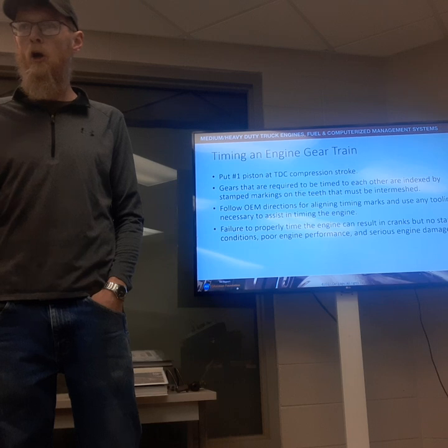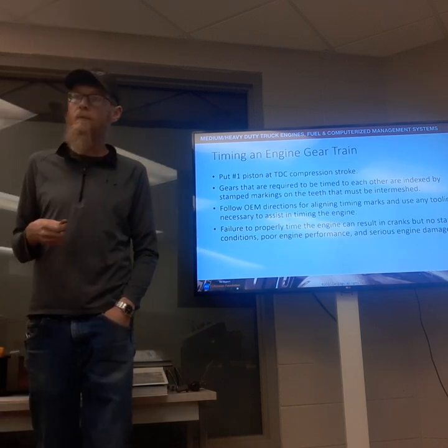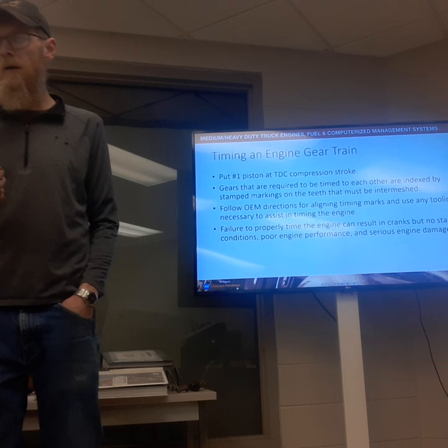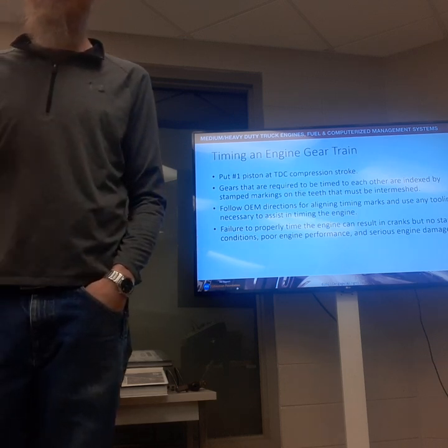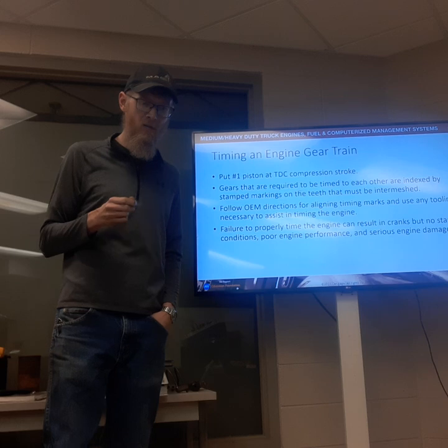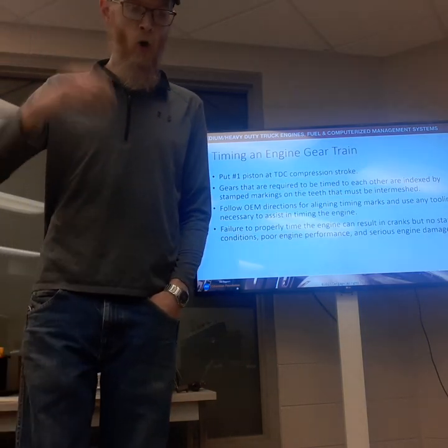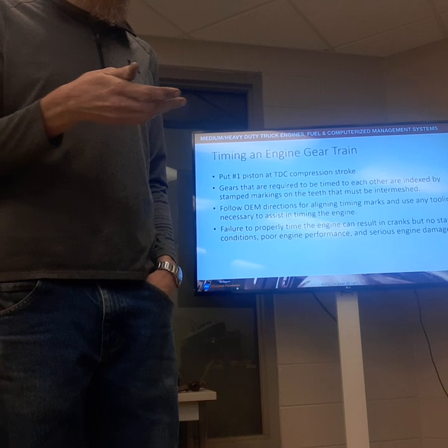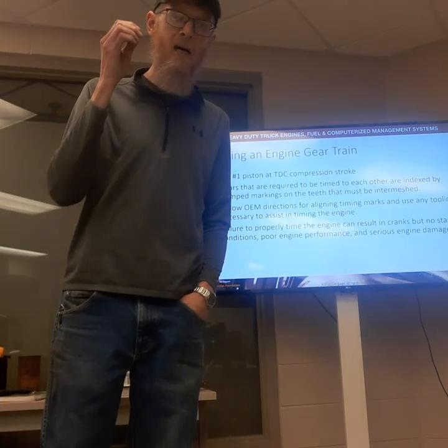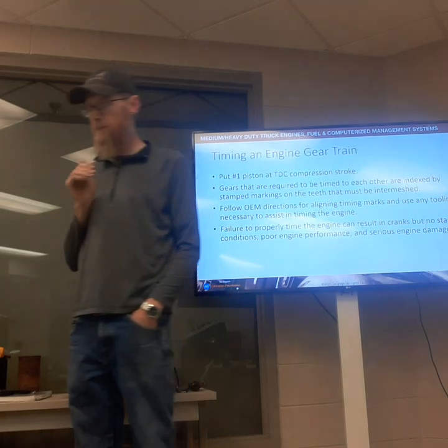And if you don't recall, when we refer to timing the engine, we are talking about making sure that the intake valves, the exhaust valves, and the fuel injectors open and close and fire at the right time in relation to the piston in its travel.